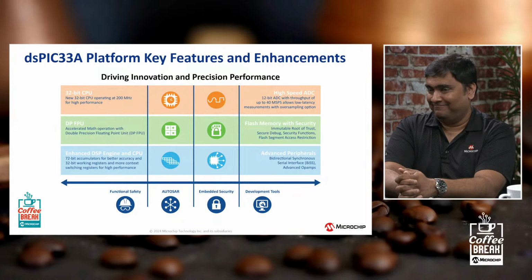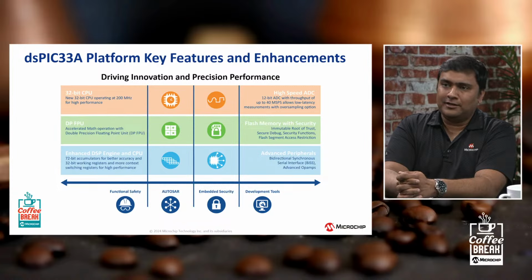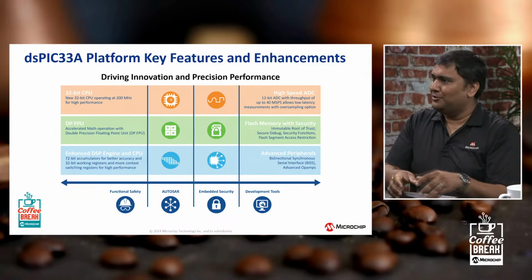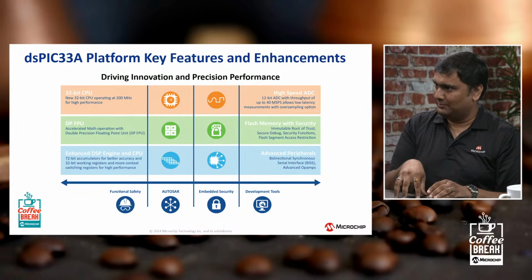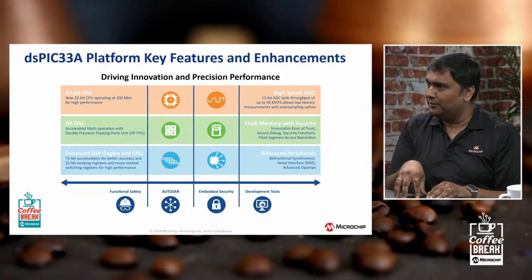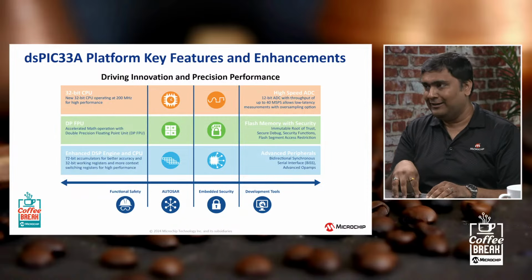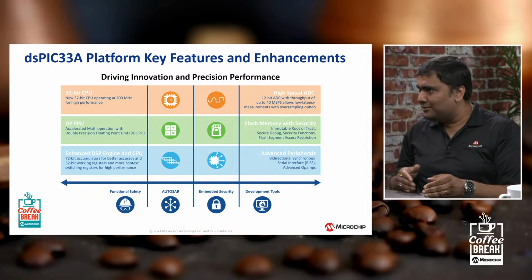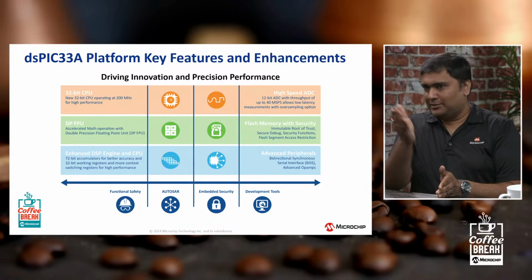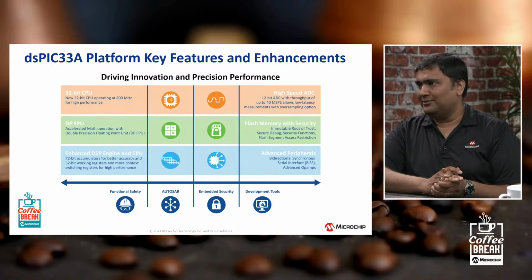So I see root of trust, secure debug, a lot of security functions built in. Yes. So there's lots of security features that have been added here because you want to make sure the firmware that your system is going to boot with is the authenticated one. The upgrade that you're getting is also authenticated. And also sometimes people try to sneak in through the debug mode. So that's why we have the secure debug as well. So lots of security features.